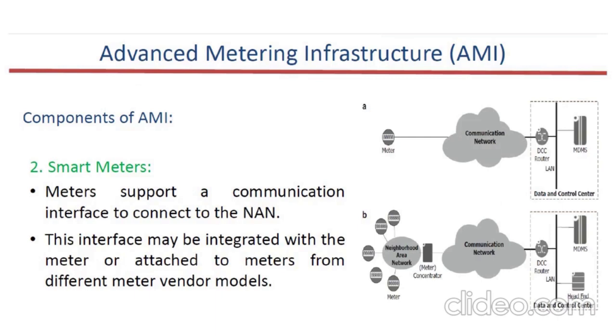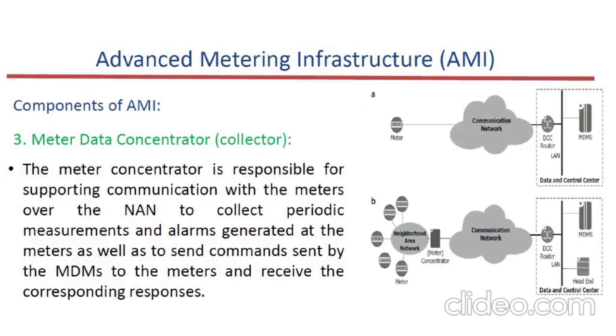The next component, smart meters, is an important component. It supports the communication interface to the NAN. The interface may be integrated with the meter or attached to meters from different meter vendor models. The meter data concentrator collects all the data, periodic measurements, and alarms generated at the meters, sends them to the meter data management system, and receives the corresponding responses from the MDMS.